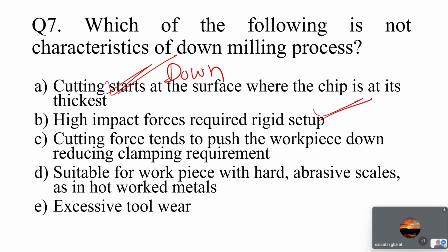Yes, because the thickness is high, impact is high, which causes chatter. Cutting force tends to push the workpiece down and reduces the damping requirement. That is correct.